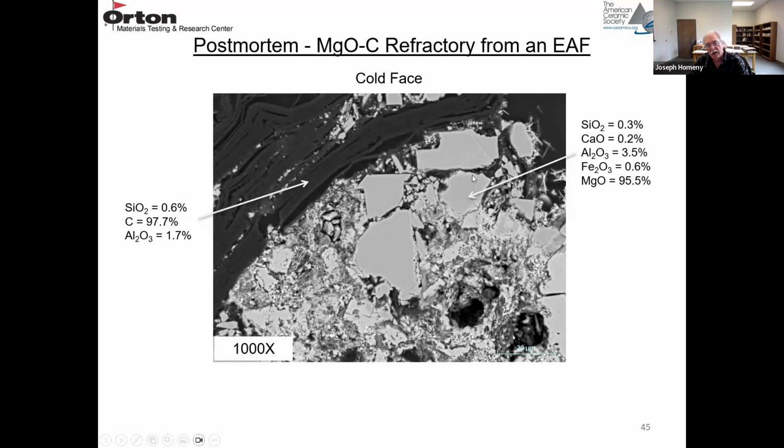And I'm not sure, but these look very dense, so they may be a fused MgO in the fines to improve the corrosion resistance. Then the balance here, there's a lot of finer MgO crystals. The balance is the matrix, which is the fines plus the pyrolyzed resin in the form of carbon.